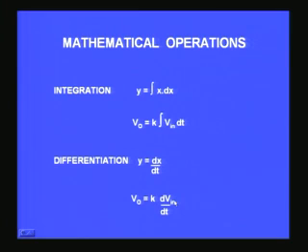Before we go to that, we will try to look at the first circuit, which is actually a multiplication by a constant, which is nothing but a normal amplifier, but there is a difference. We have already seen one amplifier which can be treated as an amplifier which can produce multiplication by a constant factor, that is the non-inverting amplifier, which we have already discussed. V output is equal to 1 plus R2 by R1 times V input, where 1 plus R2 by R1 is our k factor, the gain factor, the multiplication factor. You can choose R2 and R1 corresponding to the value of k that you want, so it becomes a simple multiplication by a constant factor amplifier.